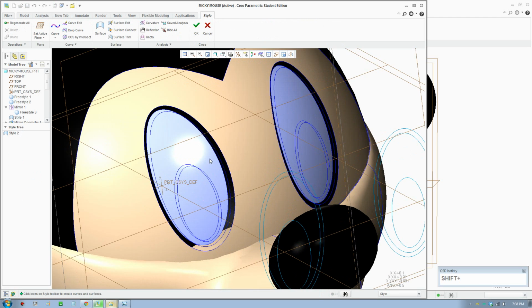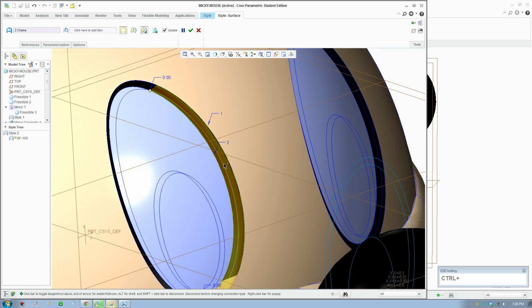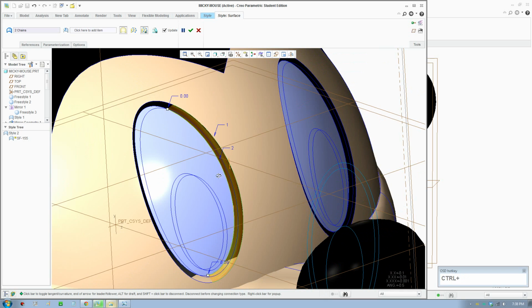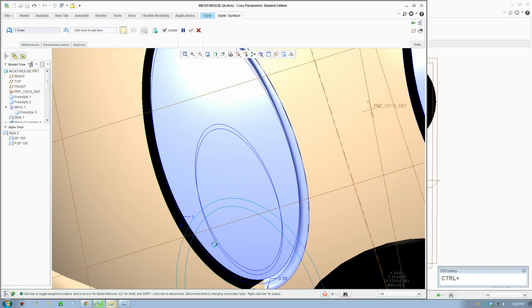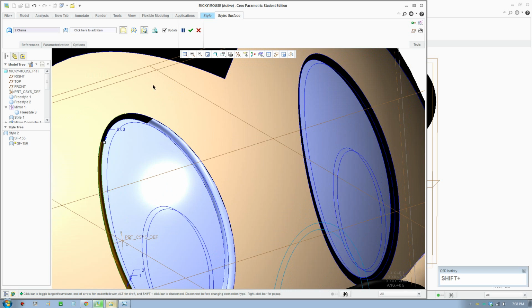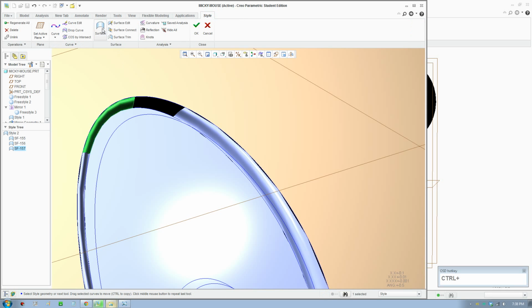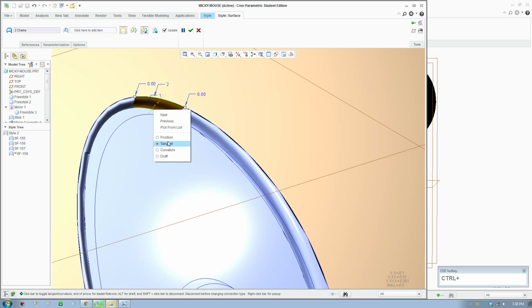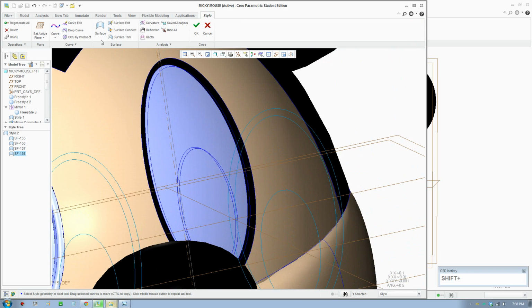Okay, so create a new style tool, and I'm gonna create the blends between the eyes here. Click on surface, click on that, and make sure this is on curvature, so there's a round blend, so accept that, and go ahead, create the surface for the rest of the eyes. Do the same for the right side. Get a surface.